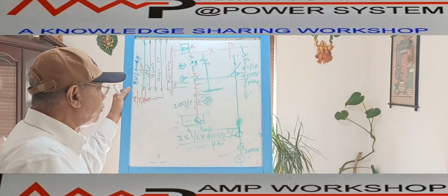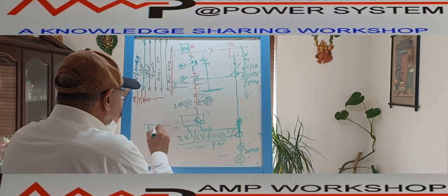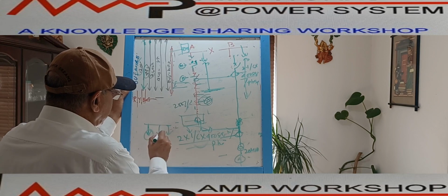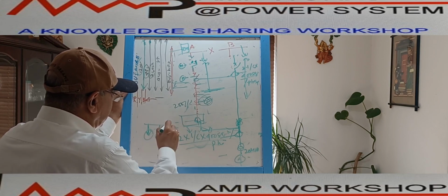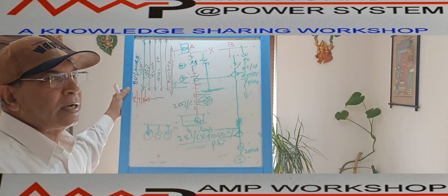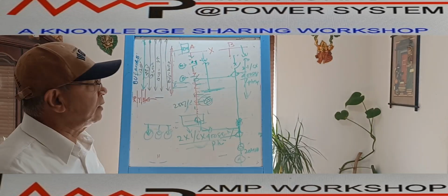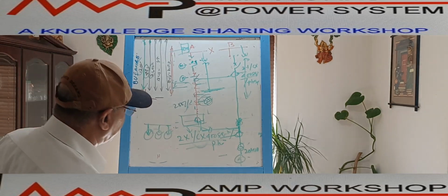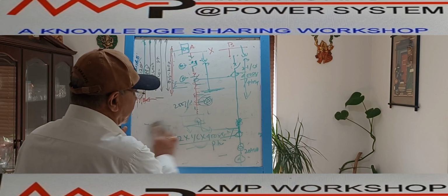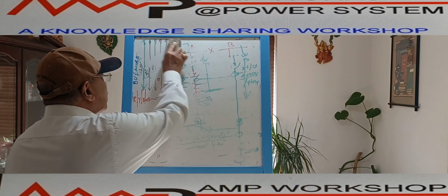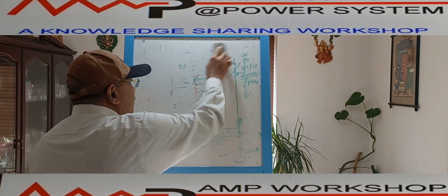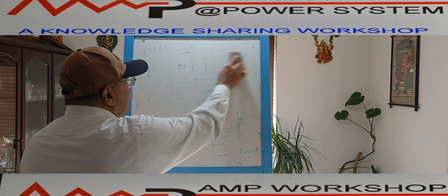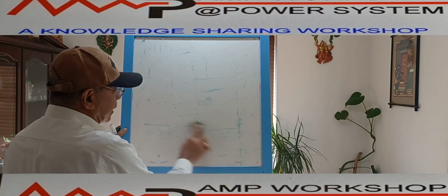If there is space, we can also show the various outside field interfaces. From here, suppose it is going to PMS, it is going to DCS, it is going to the control panel, that also we can show on the single line diagram. These are the various ways we can represent the overall single line diagram. But at the end of the day, when you complete the drawing, it will be showing all the feeders from the switchgear connected to bus A and bus B, including their cable sizes. Okay, that is the way we make the single line diagram.